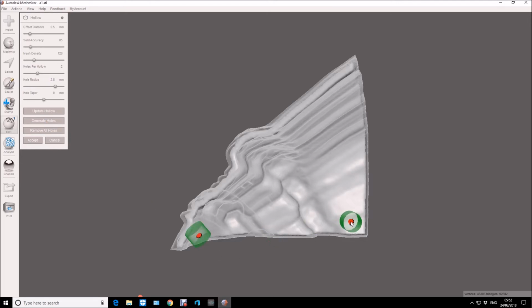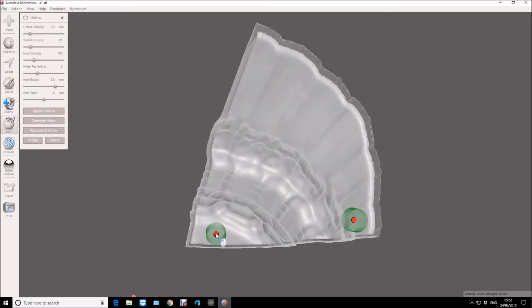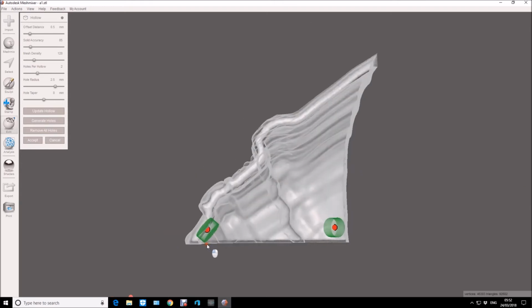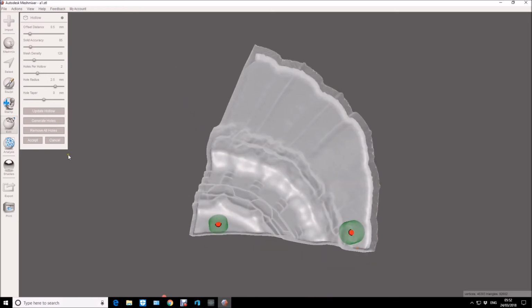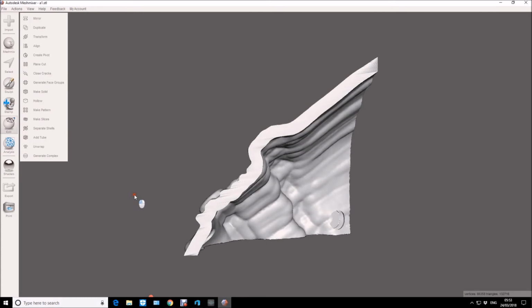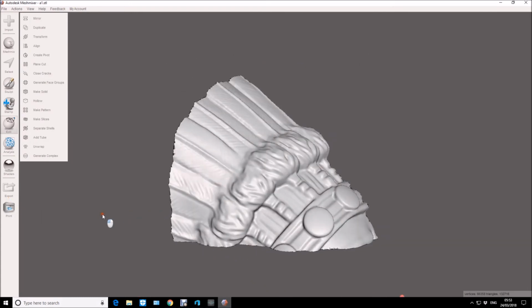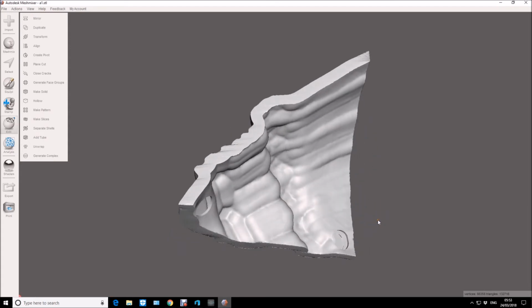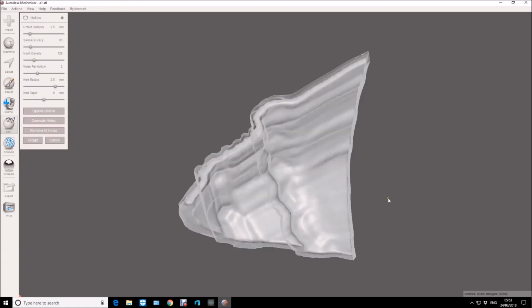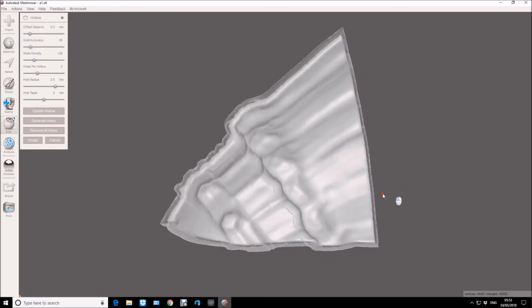I will actually use the holes though. Most of the times I do it manually, but because there's so many parts I've decided just to use meshmixer for this. Alright, be careful when you're actually placing these down, because sometimes they will punch through to the other side. So click accept. And as you can see there on the right hand hole, just there, it's actually punched through a little bit, so we'll Control Z to undo it and try and find a better position for the hole.